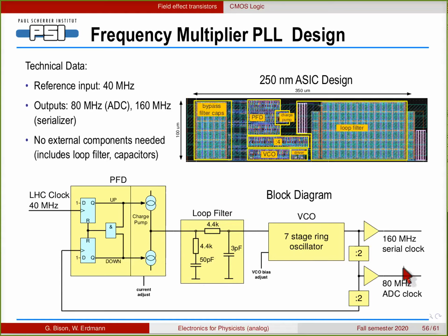voltage-controlled oscillator. And then if you don't feed back the signal directly, but you divide it by 2 using basically a 1-bit counter or dividing it by 4, then you can actually achieve a frequency multiplication. So now you come out with 160 megahertz that you generated from these 40 megahertz, and they are locked in phase. So this is called a phase lock loop, or PLL.